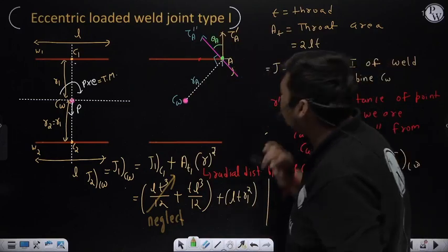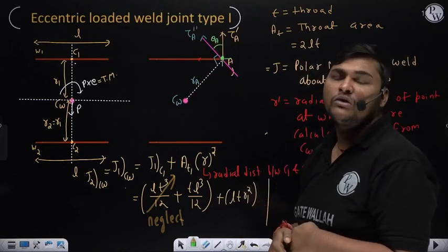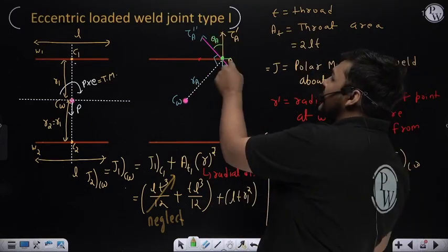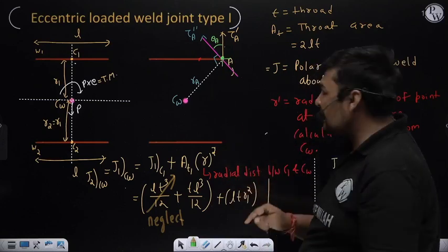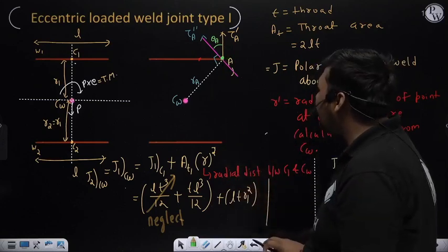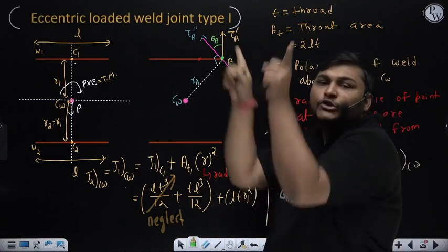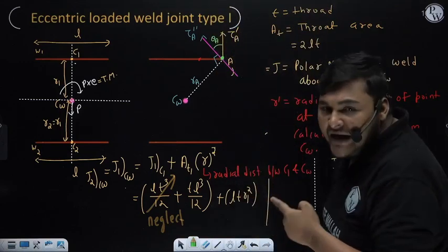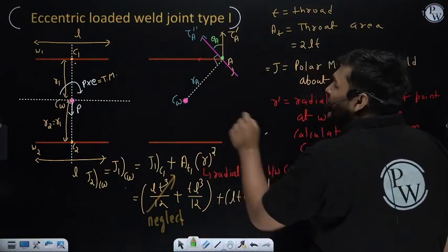This is also correct. This direction of secondary shear stress is also correct. But in this diagram, the tails of both vectors are not coinciding with each other. To find the vector angle, first draw both vectors such that their tails coincide and the arrows of the vectors go in the outer direction. In that case, the smaller angle between primary and secondary is known as the vector angle.